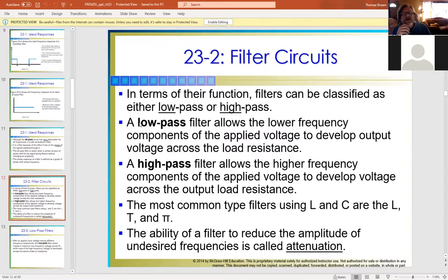So we go through and look at them. And again, all of these filters are RLC circuits, different types. We can design them in specific ways. We set up criteria and then we go, okay, we want to have this particular circuit. So we use the formulas and juggle it around and we get our componentry listed out and experiment with it, make sure that it works with these specific frequencies and there are no aberrations, if you will. But yeah, the most common are the L and C componentries. There are other ways to make filters, but these are the cheapest and most economical. Really, really.